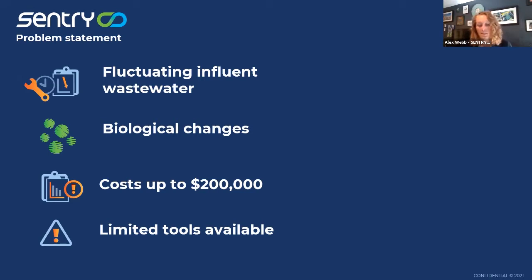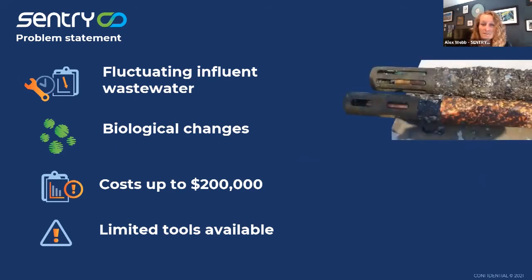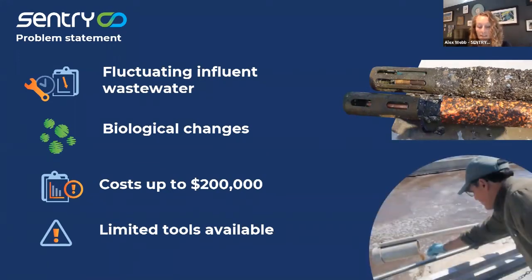You have variations in how the biology reacts to what's coming in. You also have sensors, which are not necessarily built for a wastewater environment and must be cleaned or changed regularly, or costly, labor-intensive, and limited manual sampling, which only gives a snapshot of water quality data and often only gives it a few hours or even days later.